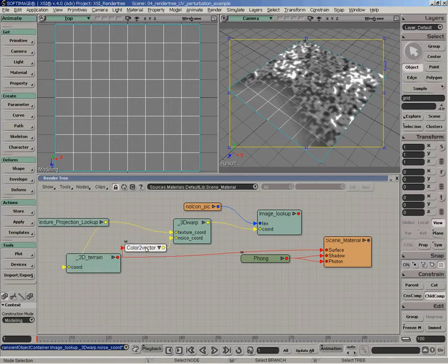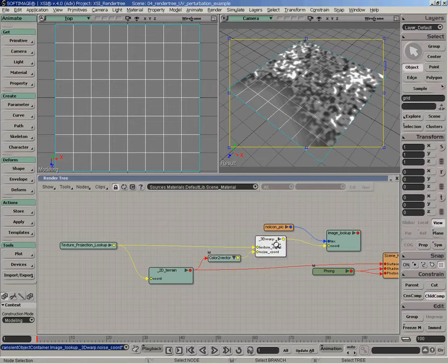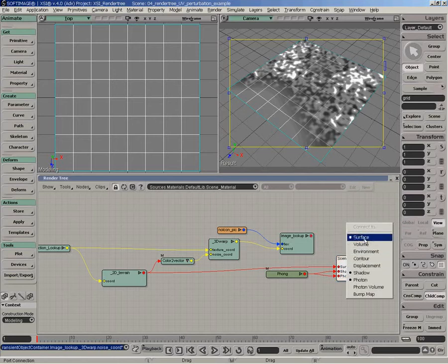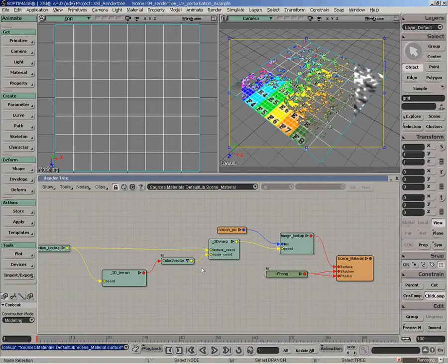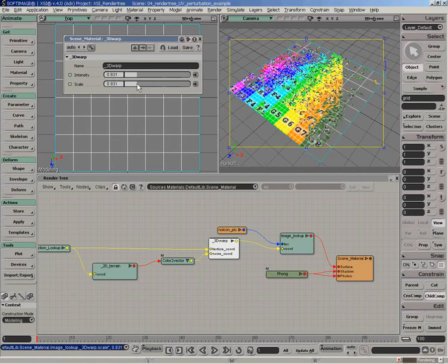So automatically XSI, or the render tree tool, will do an insert of a conversion shader. In this case, it's going to map the RGB to XYZ, and then we can connect the actual image to the surface. Now what we can do is use a terrain generation to start to dissolve a texture. And we can start to animate this.